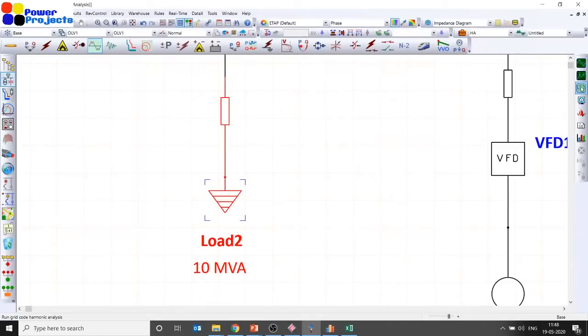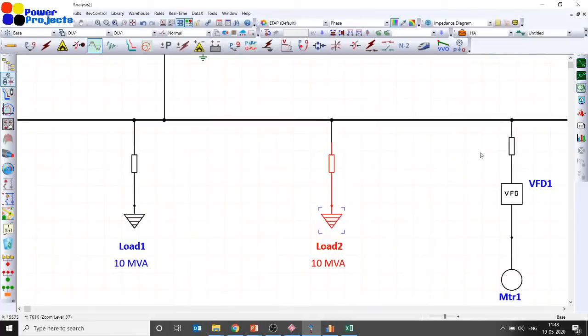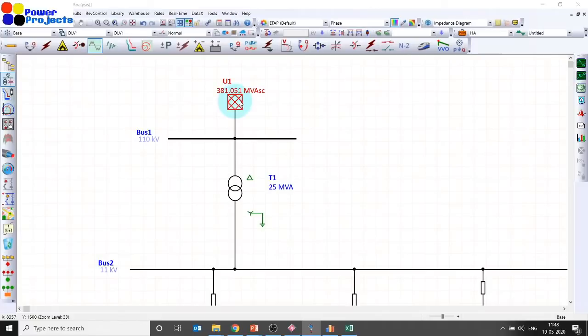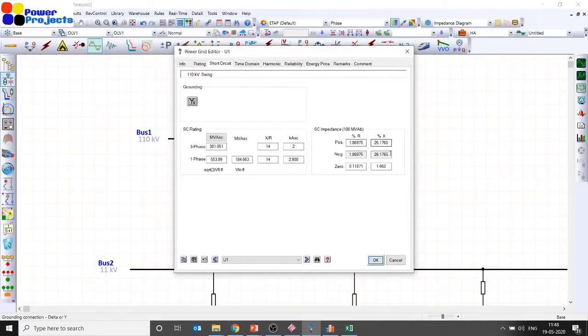Please explain why the voltage THD is increased when the short circuit level is reduced further. The grid short circuit level has an impact here. You can see in the simulation that the harmonic current is the same, but when we reduce the short circuit current, the source impedance increases. I am comparing the 20 kA short circuit and 2 kA short circuit, and you can see the impedance. The increase in impedance results in voltage distortion at your point of coupling. That's the real reason why the harmonics are increasing.